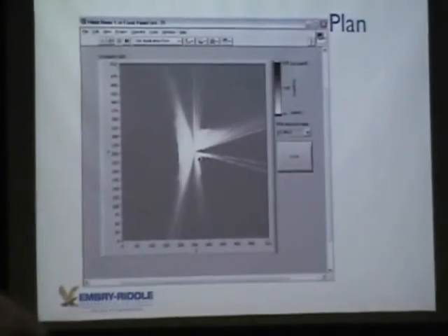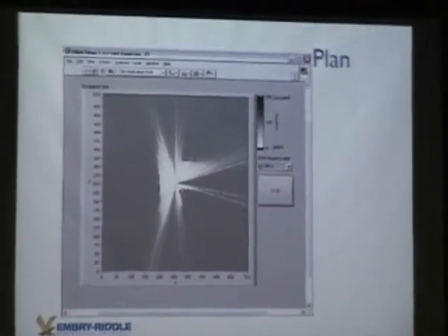Basically, we assume that the mothership has a processor on board that can communicate. The key thing that we do is take the sensor data and integrate that into a map, and that's what we use for all our high-level processing. And this is an image of one of our early sensor tests where we took that data as the vehicle's rotating, and over multiple rotations we combine it into a local perceptual map.